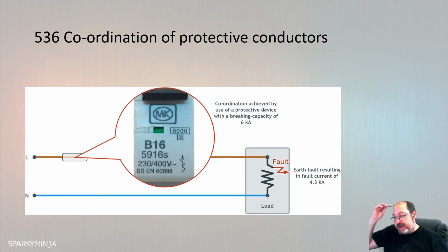The fundamental thing is, if that fault occurs on that circuit, overcurrent protective device 21 should be the disconnecting device. If overcurrent protective device 1 was to disconnect, then overcurrent protective device 22 would also be dead, and that is what we call poor discrimination, or, well, what we now say is insufficient selectivity. I hate that term. Alright, so we always want the point of isolation to be as close as we can to the event.